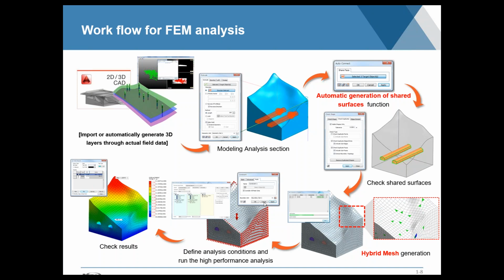We saw last week an example following the sequence for a static case. We didn't go into the excavation stages, but if you recall, most of the time-consuming aspect of modeling in 3D will be split between setting up the geometry of the model, and in 3D we now have tools where you can even import borehole data as well as topography or terrain surface information. And then we went through the process of extruding a tunnel face, making sure everything is connected, meshing it, applying our boundary conditions and our loads.